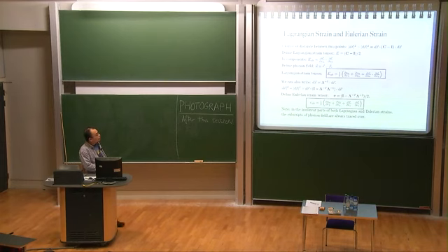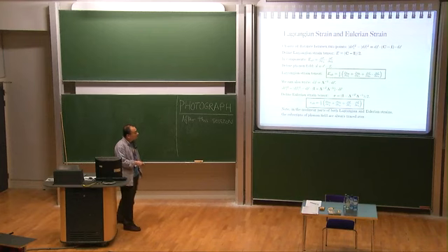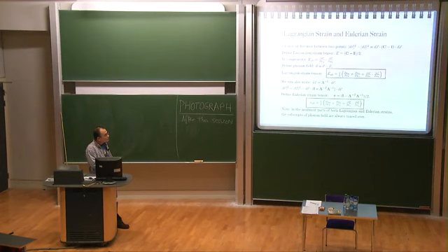We can express the little e, the Eulerian strain tensor, in components like this. Now I found there's a mistake here. The sign is negative in the nonlinear part. But again, we have to notice that vector u is dotted into vector u, so the index of u is always traced over. This is important.